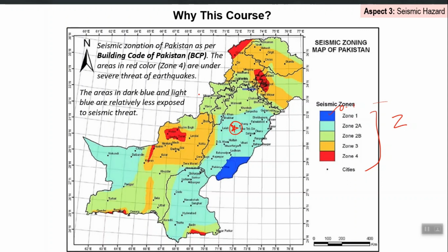Currently, it is all about resolution also. If you are doing something at a very high resolution, you are giving more importance to all the details, which means you are going more accurate, right? So site specific PSHA is one of the things which should be performed before every important project. If you are designing a 50-story building, ideally it deserves a site specific PSHA. If it is located somewhere here, you should not directly rely on these numbers. You should go for site specific PSHA.